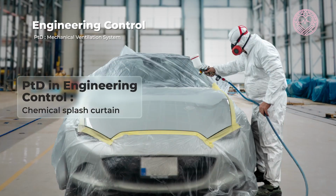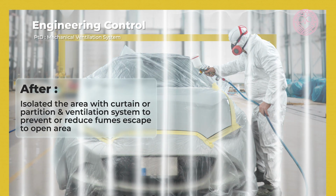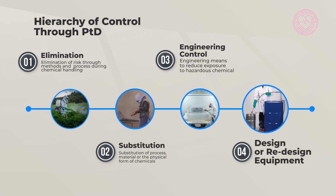PTD in engineering control. Chemical splash curtain. Before, operator uses solvent chemical to clean parts and the fumes may expose workers in the open area. After, isolate the area with a curtain or partition and ventilation system to prevent or reduce fumes that escape to the open area.